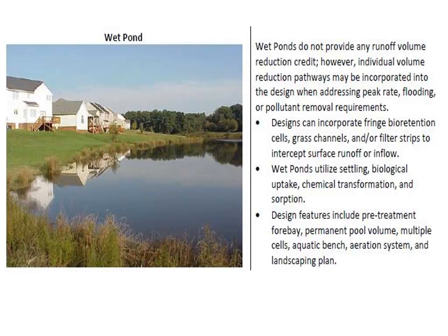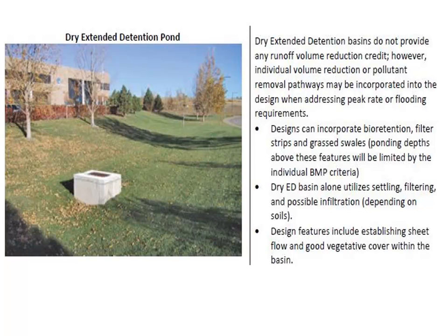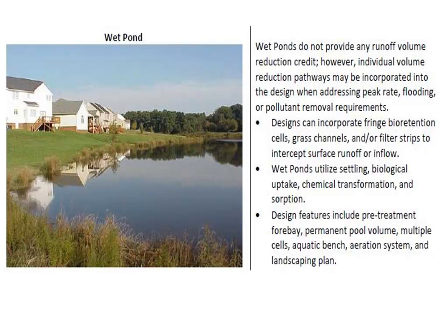A wet pond, on the other hand, is meant to have some freeboard so that you could put additional water into the pond during a storm event, but then it's not ever meant to drain completely all of the way. And the advantage of a wet pond over a dry pond is that a dry pond like this can't support fish. It can't support a lot of the same kind of wildlife that a wet pond would be able to if it has water in it all the time. Plus, it's very scenic. People like to have a water view.